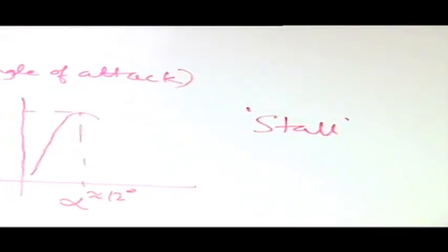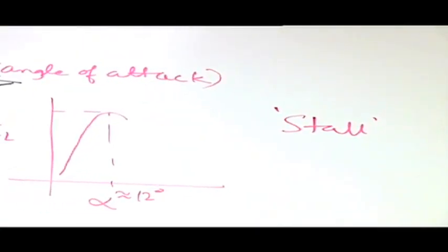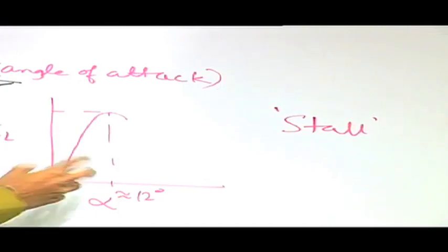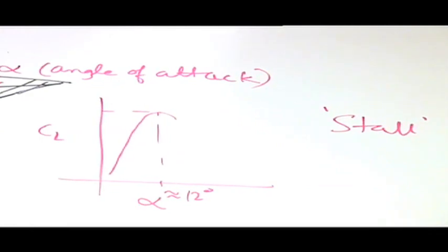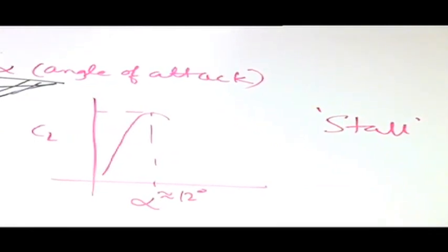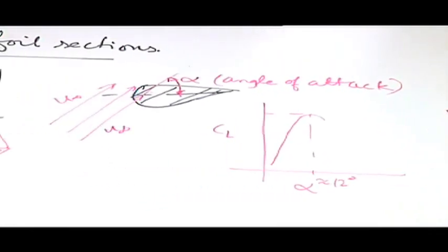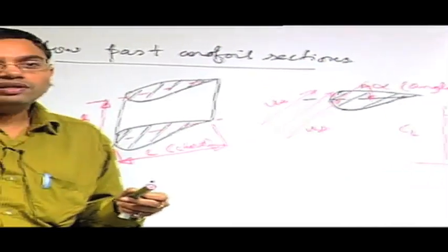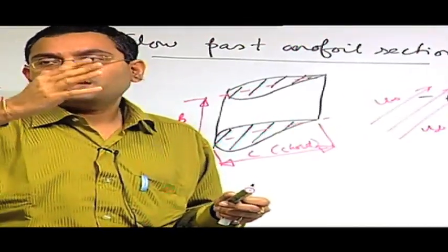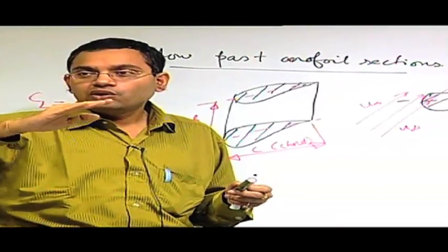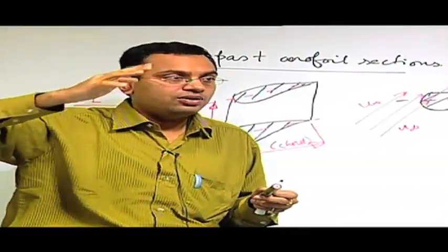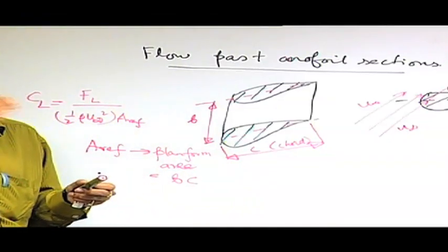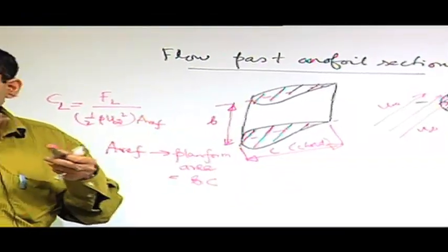One of the important objectives is to generate a lift force. So you may increase the value of alpha to generate a greater lift force if you want to go to a greater elevation. If the aircraft has to have a higher elevation, it should have its aerofoil wing section oriented in a particular fashion with the relative velocity of the wind outside, or the relative velocity between the outer ambient and the aircraft.